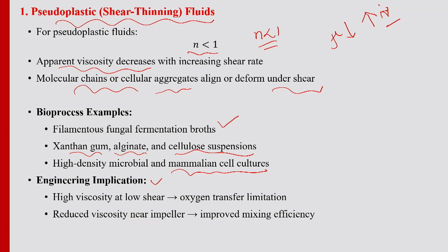The engineering implication, as discussed already, is high viscosity at low shear, so oxygen transfer limitation can occur. In the same way, viscosity decreases near the impeller, so we have to improve mixing efficiency.